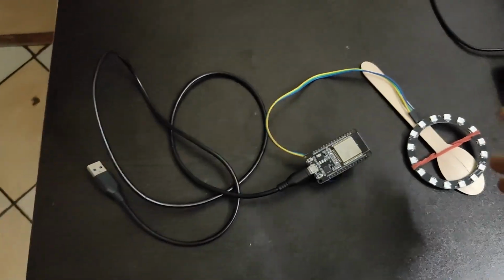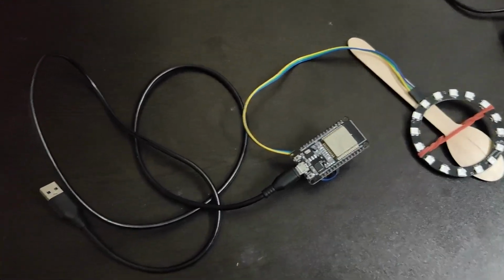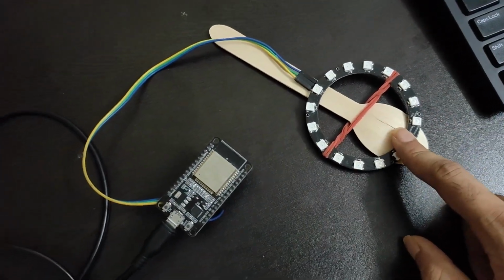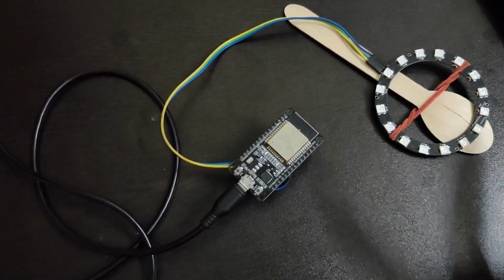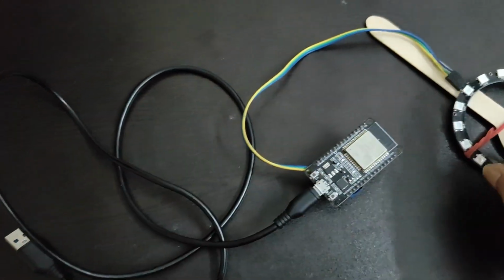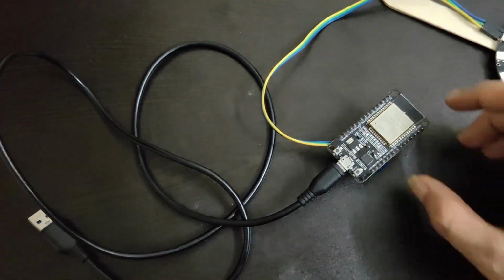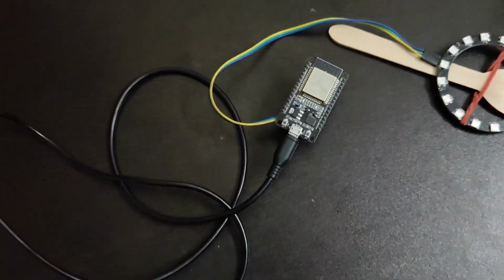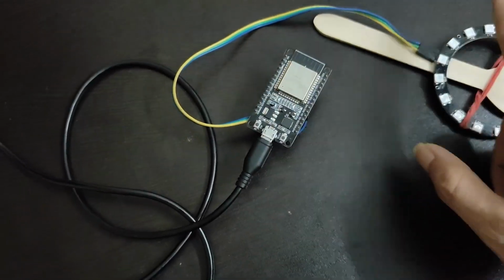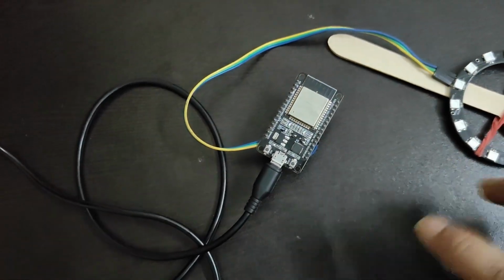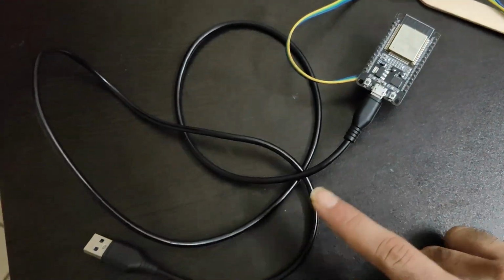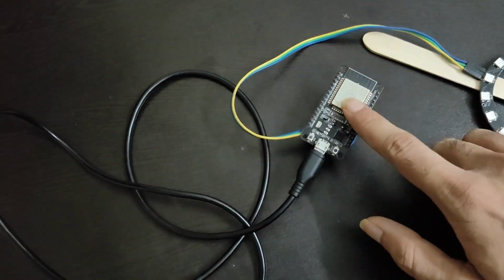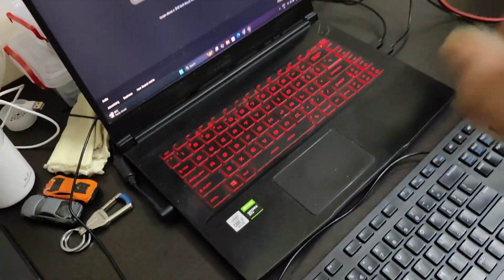Okay, so here you can see, here we have the devices. You just need this ESP32, this NeoPixel LED, and you have two options. Either you can buy jumper wires like I did. Here you can see, this is called a jumper wire, which is plug and play wires. Or you can just directly solder the pins from this point to this point, although I will prefer this jumper wire because you can use it for different purposes. And you need a micro USB cable to upload the code into this ESP32 through the laptop.